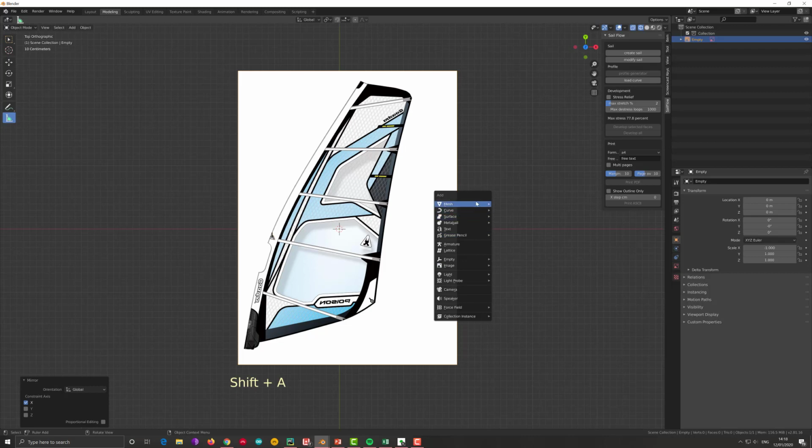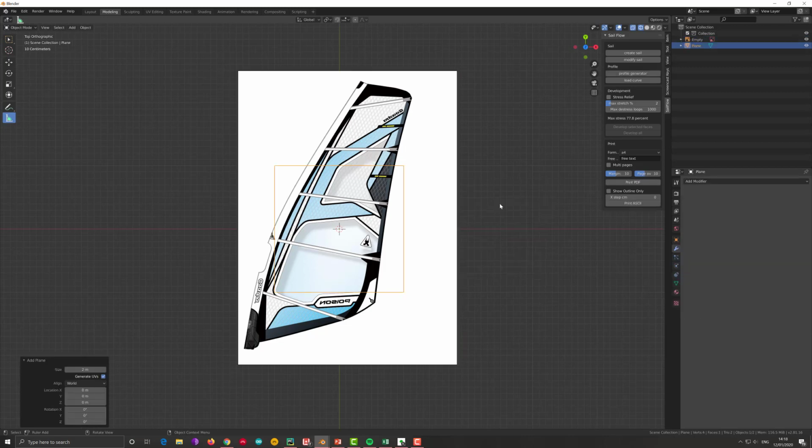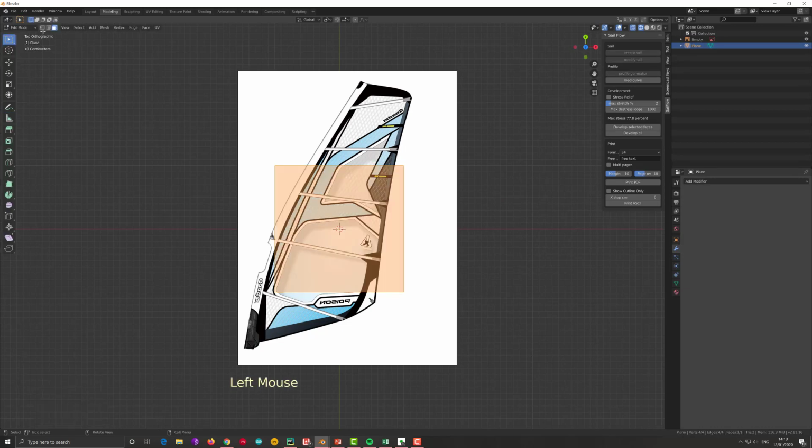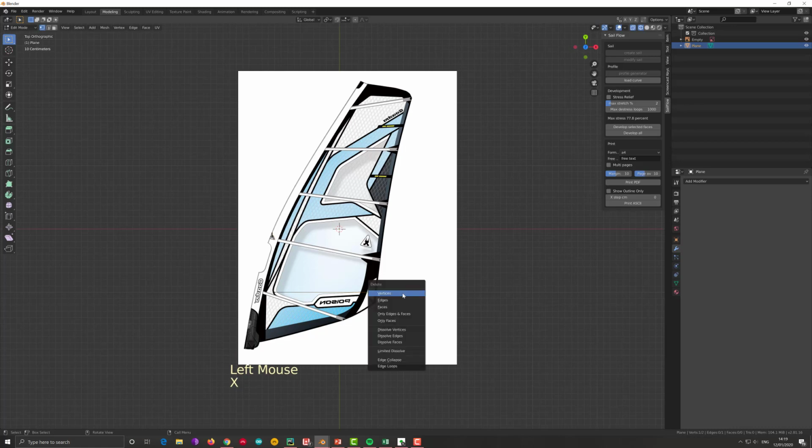It's a bit of a custom design, so the first thing we have to do is create a plane, which we're not going to use, and go to edit mode, where we can select the vertices and erase everything but one vertex. So I select the vertex, I press X and then delete the vertex, and then I remain with only one. It's not very visible, I hope you can follow a bit.